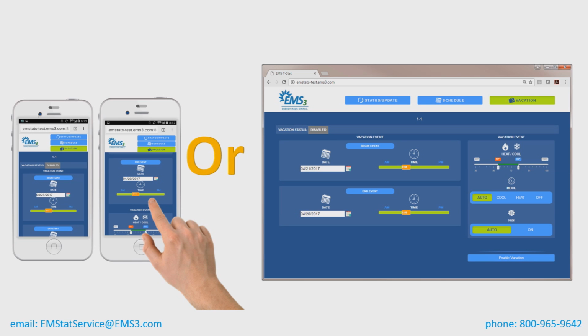First, we want to set our begin date and time and our end date and time. This is fairly straightforward. You want to set the day and time that you want your EMStat to assume this new temporary setting called begin event. Then set the day you want it to return to the normal schedule, end event. You'll notice that there's no need to set the end event time. Since vacation mode is in 24-hour increments, whatever time you begin will be the same time that vacation mode ends.